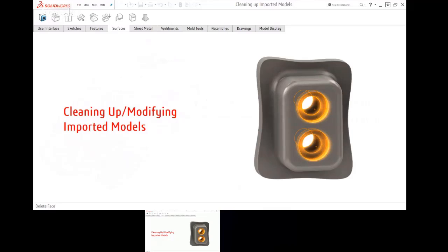So like in this case, I import the step file and I just need to delete the holes. Okay, so this is perfectly applicable to a sketch and extrude, kind of a hack and fill type of approach, right? We would just go sketch a big block on there and extrude it up. Nothing wrong with that solution. It's just not very elegant.